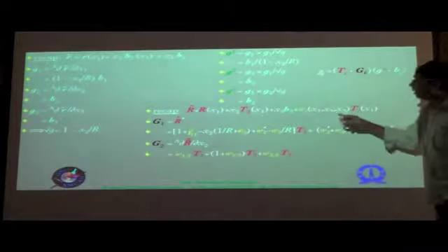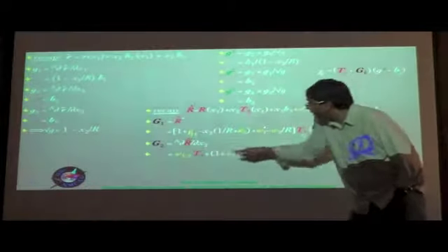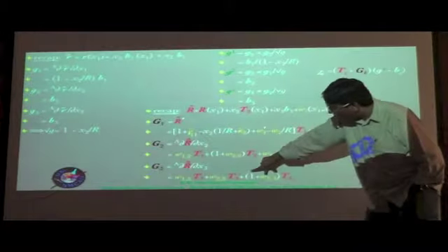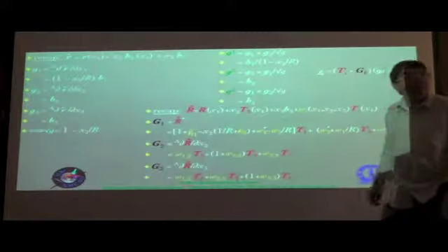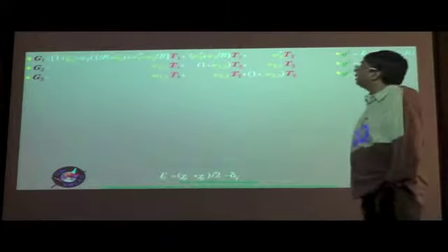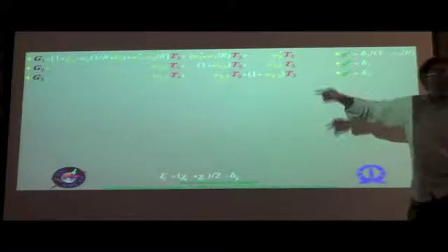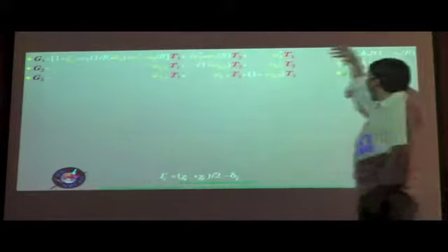So each one of the wi's with respect to 2, you have w1,2, w2,2, and w3,2. This T2, of course, as I said, comes from this term over here. The G3 is very similar to that. So you see that instead of a 1 plus w2,2, you have a 1 plus w3,3 here. The rest are all derivatives of the warping measure numbers with respect to the x3 direction. So now, this is the summary of what we determined in the previous slide for the covariant base vectors of the deformed configuration and the contravariant base vectors of the undeformed configuration.